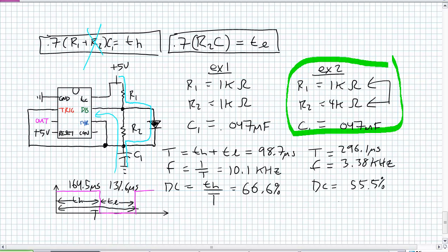Be aware that we'll have some current going through R2 in that particular configuration. Let's say it was plus to minus 0.7 volts. Realize there is plus to minus 0.7 volts across R2, so a little bit of current will go through because, again, elements hooked in parallel have the same voltage across. But let's just say it's a magic diode. Reach into the box, you pull out your magic diode, there is no voltage drop across it.